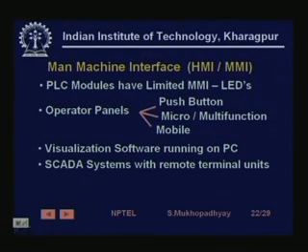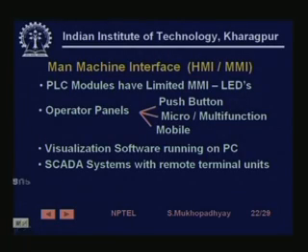Sometimes, especially for power applications, you have remote terminal units, that is, the system is working in, let us say, unmanned stations, and from kilometers away you want to get a view of what's happening, let us say which of the transmission lines are on and which are off. Such a system is called a supervisory control and data acquisition system, often called SCADA. SCADA systems with RTUs give operators a visualization of what is happening quite far away in unmanned places. They also serve an MMI purpose.